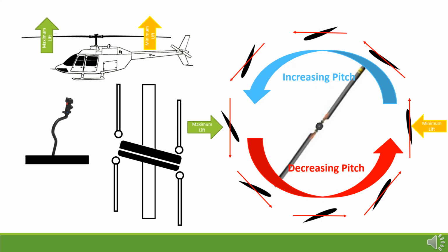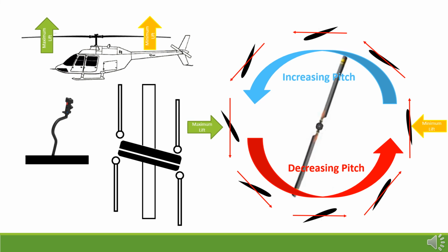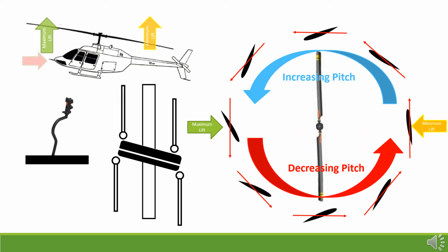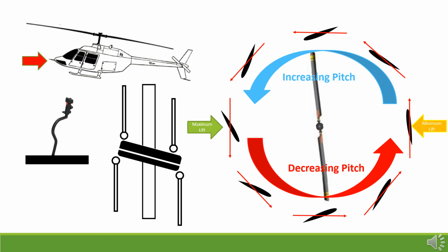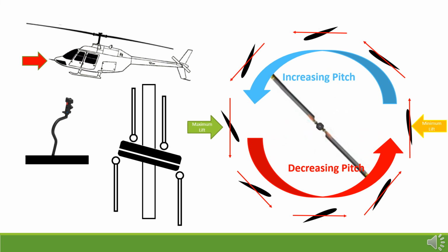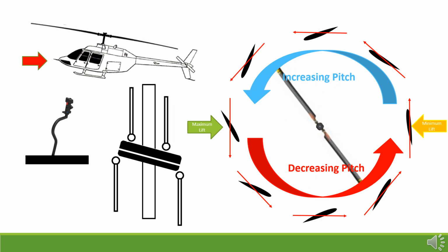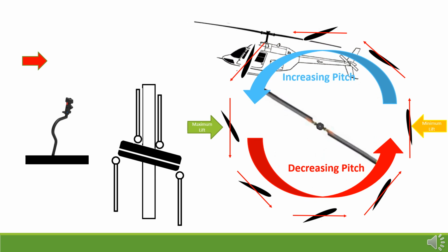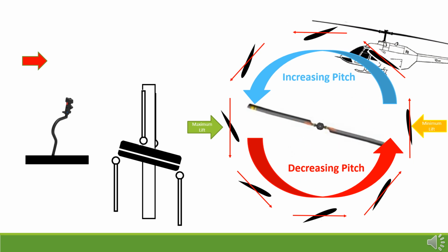When the rotor disc rotates backward, it produces a force acting toward the rear of the aircraft. It also makes the nose pitch up, which increases the rotor disc tilt and increases rearward acceleration. A corresponding increase in collective control would be required to keep the helicopter from losing altitude as it moves backwards.